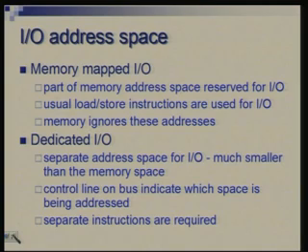As I just mentioned, in memory mapped I/O, part of the memory address space is reserved for I/O, and you can use the usual load and store instructions for reading or writing the registers which are actually located in that space. Memory is designed to ignore the addresses which fall in that range. So, let us say you are using the last 1K addresses for I/O in a given address space. If a load instruction is executed and the address is found to fall within that range, the memory does not respond, but the appropriate I/O device to which the address has been assigned will respond.